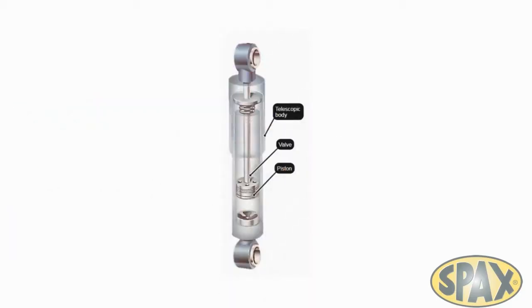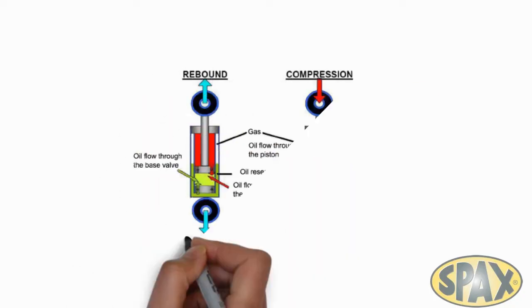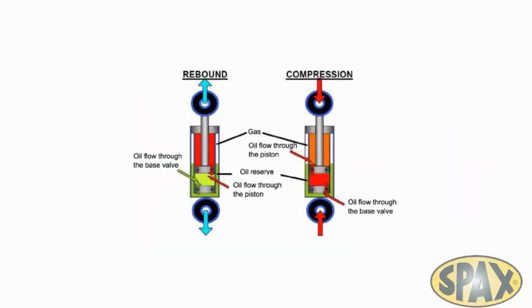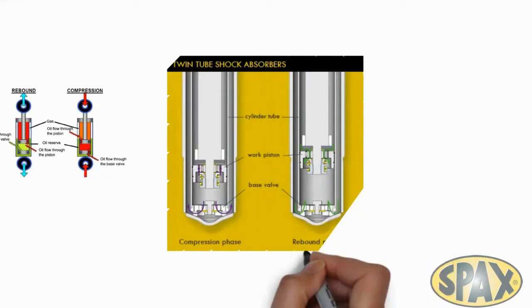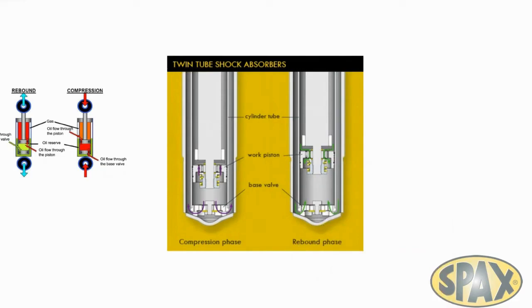A damper is effectively a piston in a cylinder surrounded by oil. As the vehicle hits a bump, the piston is compressed and some of that oil will be forced through holes in the valve block. The rate of oil transfer is regulated through a valve assembly. As the oil is circulated through the damper, whether in bump, that's compression stroke, or rebound, extension stroke, motion energy is absorbed and heat is released. Kinetic energy creates the heat and dissipates the movement forces created.